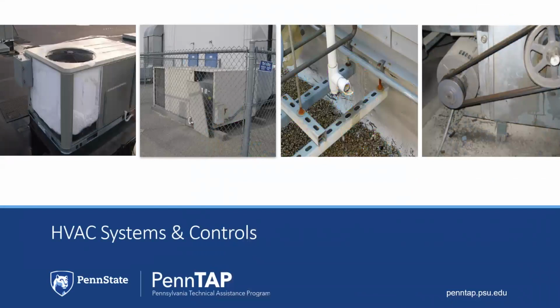After you've investigated the building envelope, you want to take the time to look at individual operating systems and review their current conditions. For HVACs, problems can occur in many of the components. You have economizers, you have refrigerant levels, fans that are operating. Are they operating during occupied or unoccupied hours? Are they cycling on and off for heat and cooling rather than providing ventilation? Understand what your HVAC controls are doing. Maybe your zones have changed. If you've done any renovations, you might have to consider your new zones, and also make sure if you have multiple thermostats now that they are not overlapping.